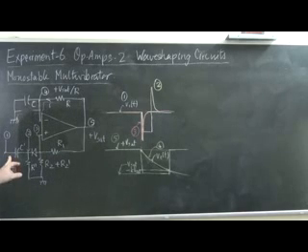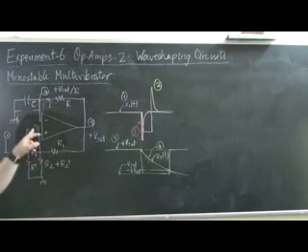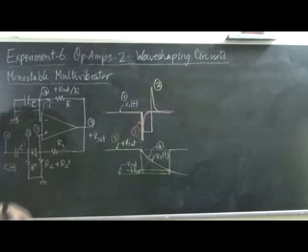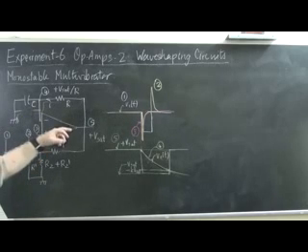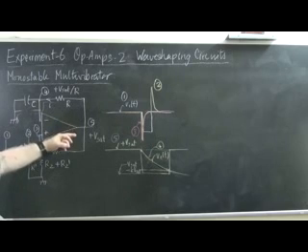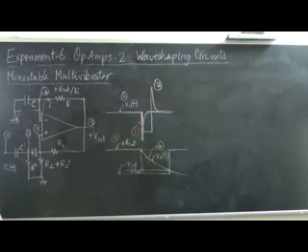A negative pulse was applied here, giving rise to a negative impulse and a positive impulse at this point, waveform number 2. Waveform number 1 is the negative pulse. Now at waveform 3, which is the non-inverting terminal, only the negative impulse is applied, and this negative impulse causes the op amp to transition from its normal state of plus Vsat temporarily to minus Vsat.